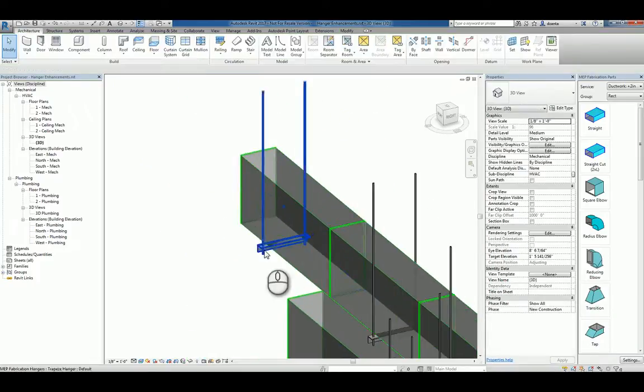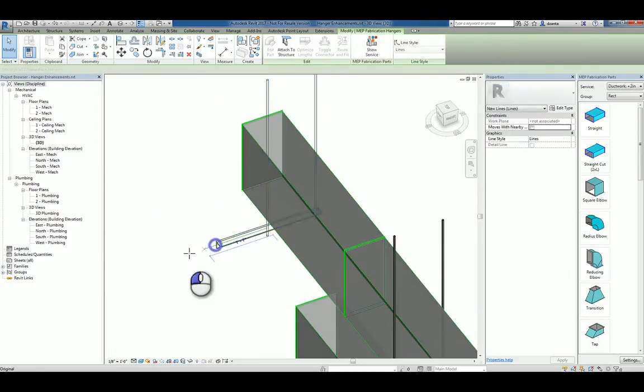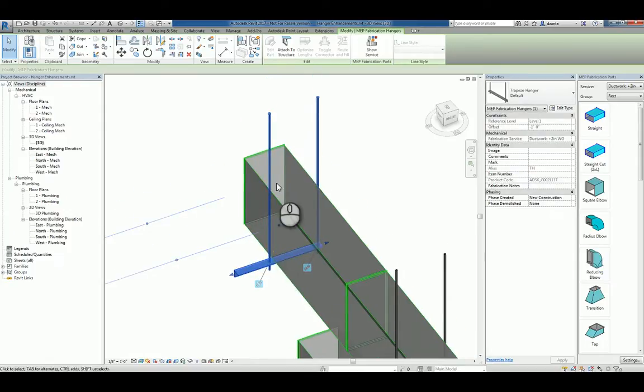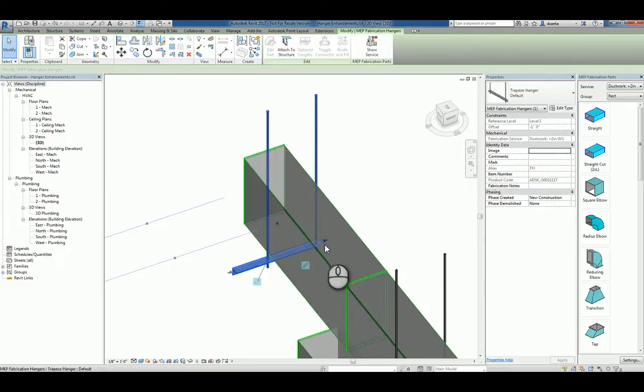This warning is because of the hanger that you saw earlier over here. If I select this particular hanger, you can notice that, again, I can pull that end, but there's also going to be little locking symbols that you can lock or unlock. And what that does is, let's say right now it's locked. So if I unlock this and I decide to move this member, that end is going to move. That doesn't look like it did anything, but if I grab and pull, it'll adjust. If I grab and pull this arrowhead here and pull, that makes the adjustment.